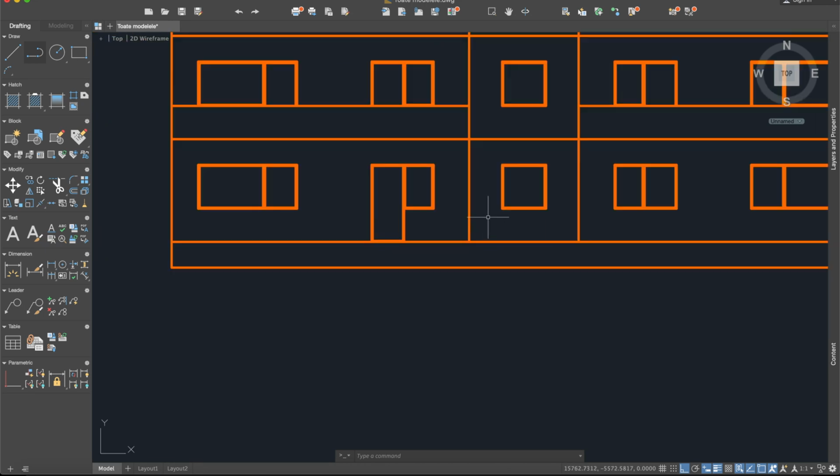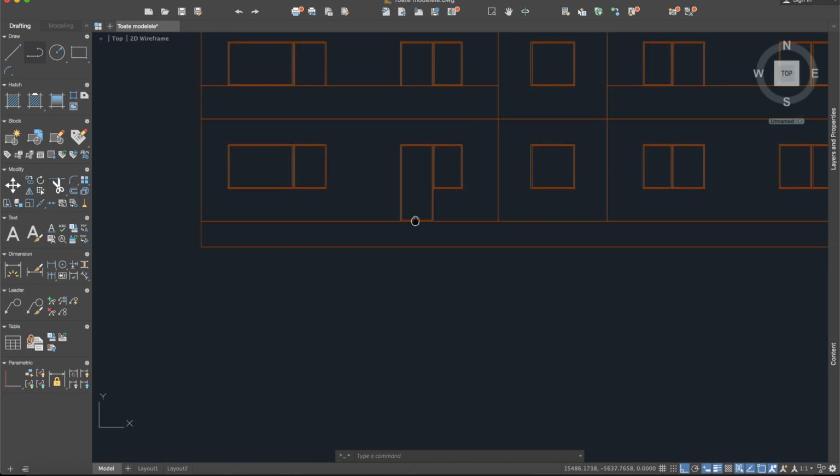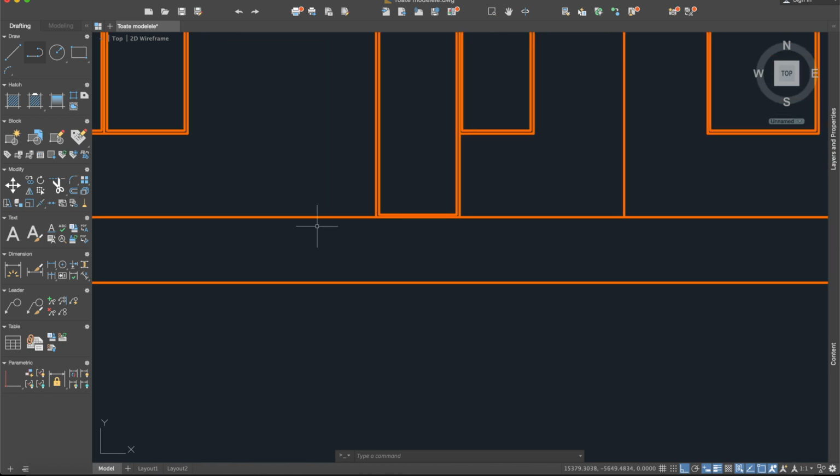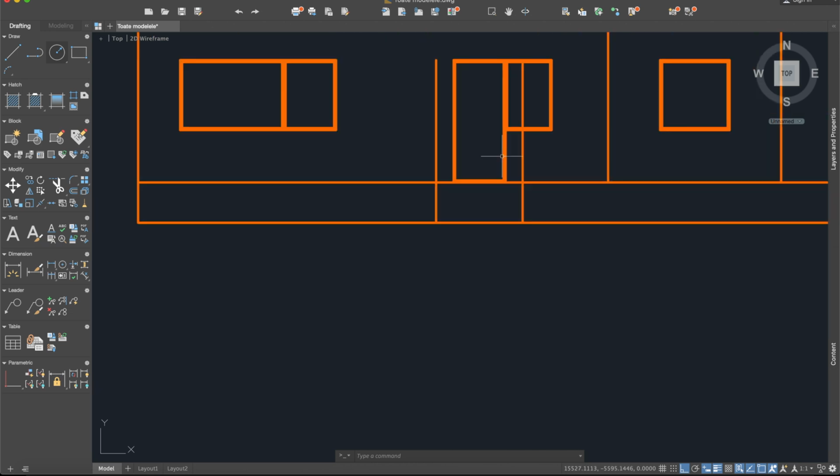And here it is. This one will be the entrance door. Pay attention. Okay, now we will draw some ladders right here. For this one, I will go with offset 30 from the exterior of this side and this side. I will extend it, and I will extend it also here. Trim what is left, select everything, enter.